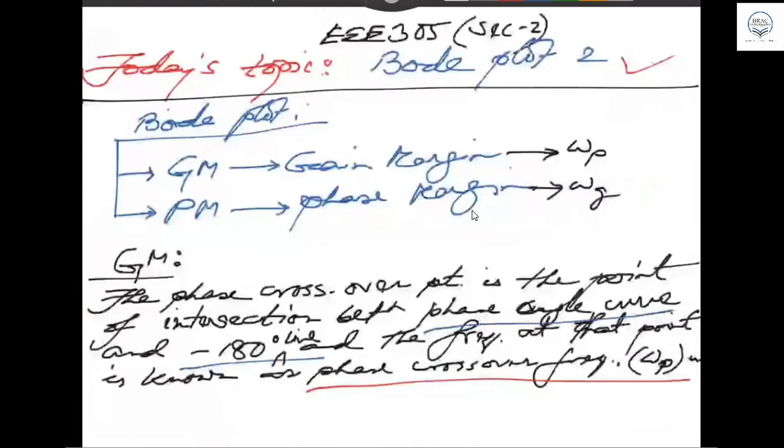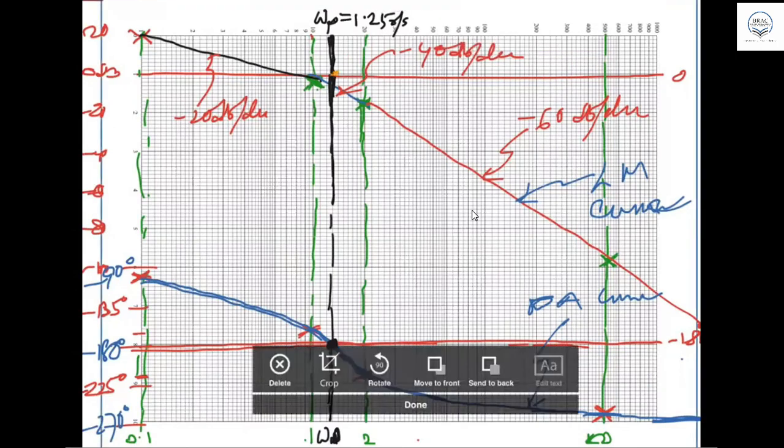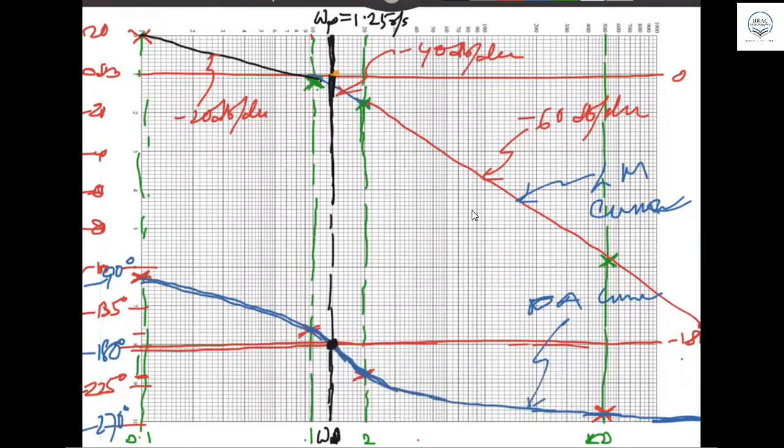Next is to determine the target, which is the gain margin. Now, from here, we are going to find what the gain margin is for this case. That one we have to find from the curve. Let's go to the curve and see here this line intersecting the 0 dB line at a certain point, and it is intersecting the log magnitude curve at this point. These are the 2 points we have to identify.